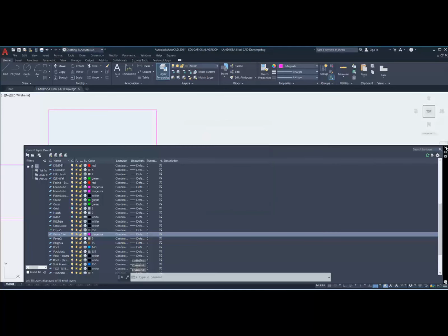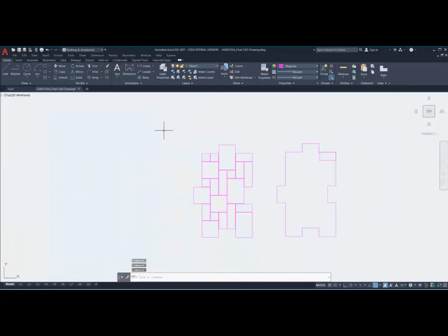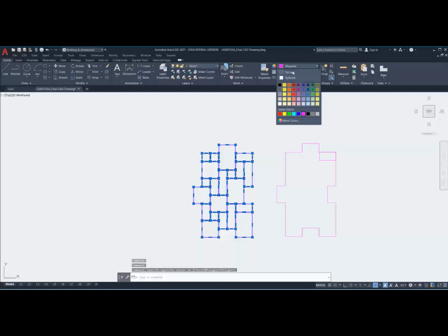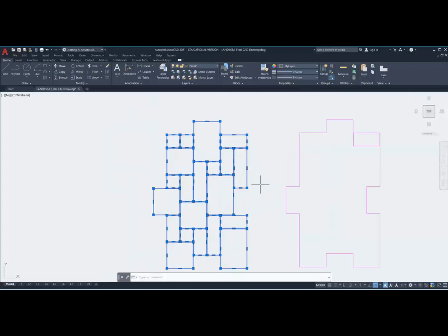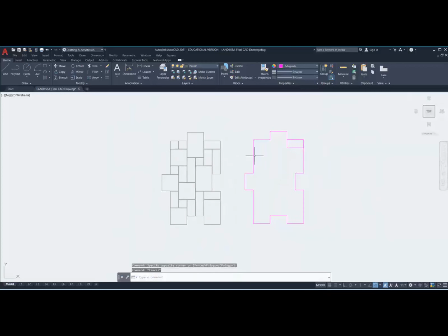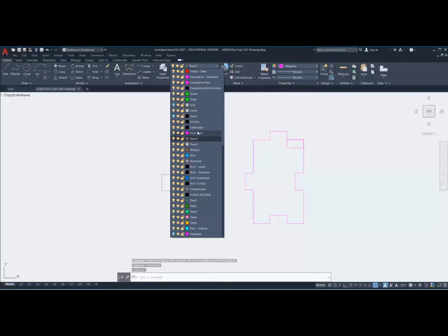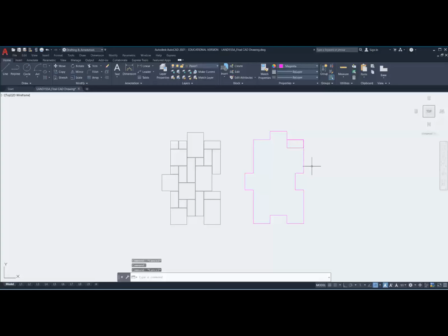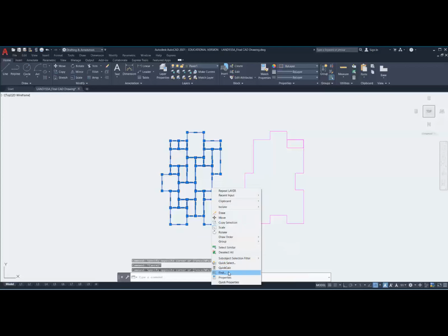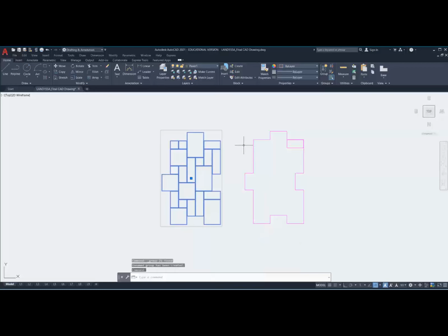Okay. Now originally I turned everything magenta because I wanted this to really stand out when I was tracing over top of it, because its original color was difficult to see. So I'm selecting the by layer process. So there's the right color. Okay. This I'm going to be putting onto that reference layer. Paver 1 reference. There we go. So there are 2 separate layers. Now this is what I'm going to be grouping, this series of elements here. So I click on it. I select group, group. So now it becomes a single entity for copying and pasting.